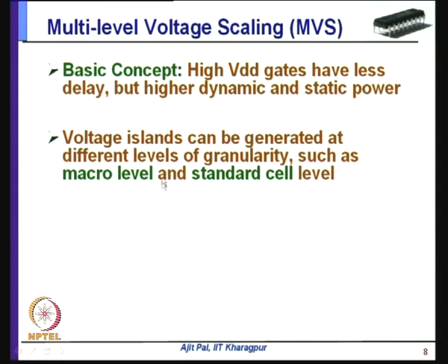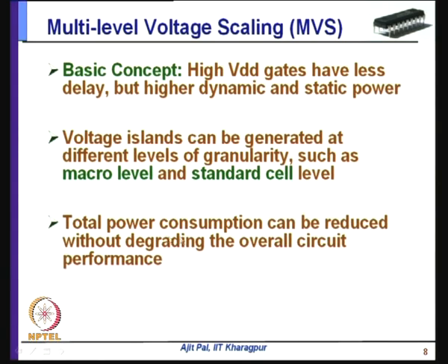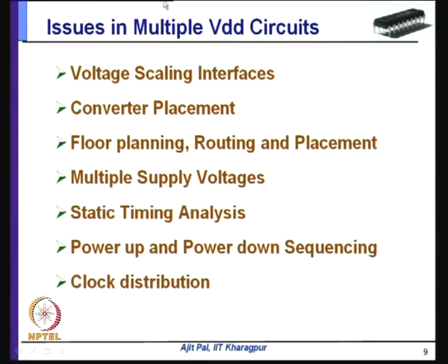Then each of these islands can operate at different voltages, and the voltages can be switched if necessary whenever the workload requirement is different, and total power consumption can be reduced without degrading the overall circuit performance. And whenever we go for multiple VDD circuits, there are a number of issues to be considered, and we have discussed all these issues in detail one after the other.